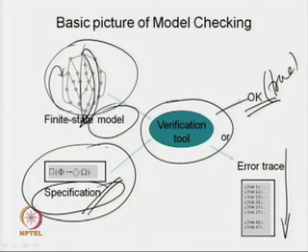So, it is some sort of focusing on the bug, and the design team can now look into the issues related to it, but it does not rule out that errors are present in other sections. They may be present in other places also, because when the designer fixes this particular bug, next time it may say the error is in some other part also. But by applying model checking repeatedly, eventually we can capture most of the errors and fix them. So, it is not only saying that it is false, but along with that it gives some indication of where the possible error is.